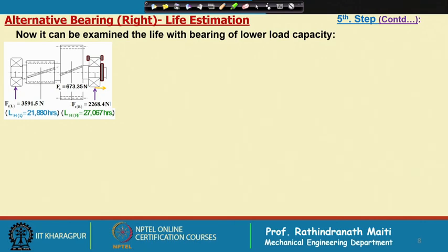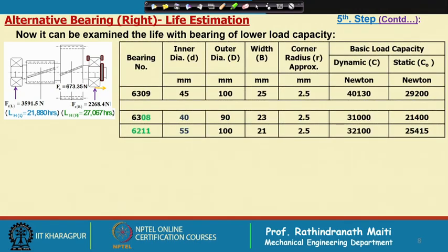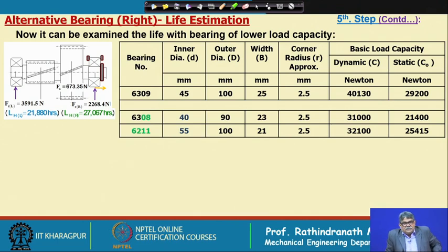What we have done in the same catalog, first of all, is that here it is not difficult to reduce the shaft size at the bearing. We initially took 45 millimeter at the bearing, where the bearings are sitting. Now, we can go for 40 millimeter easily,